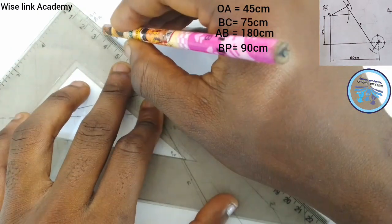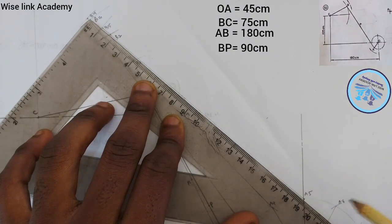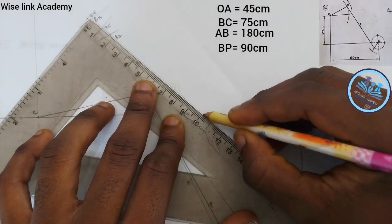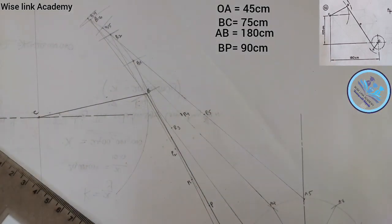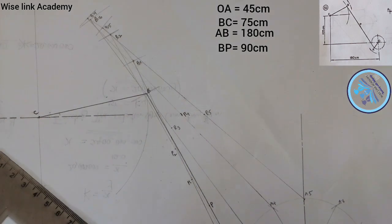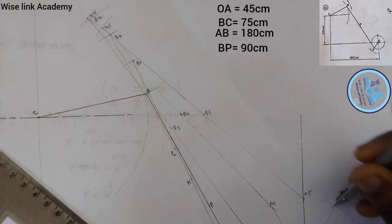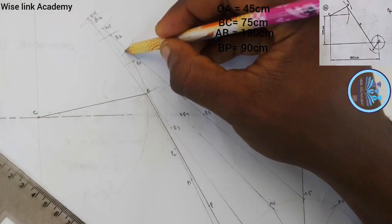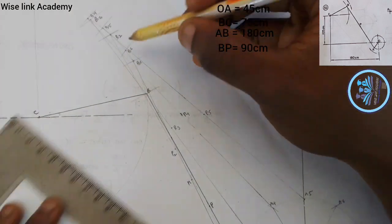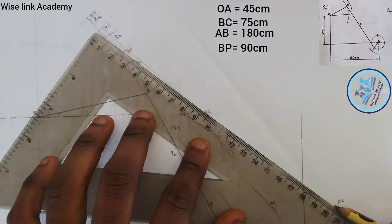A5 with a faint line, and then you measure your 90 at this point here, my point 90 here, P5. Similarly, I will take it again, same procedure, at my point A6. As you can see, my A6 used to cut somewhere here. It is cutting at this point. I call it B6. So connect B6 and A6 together this way.